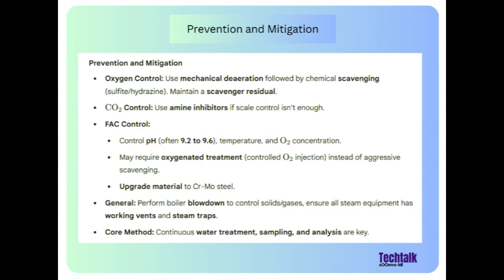Hydrazine sounds potent. It is. These chemicals react with the remaining oxygen to neutralize it. And crucially, you need to maintain a small residual amount of scavenger in the water going to the boiler. A little bit extra, just in case. Exactly. That residual is your safety net. It mops up any oxygen that might leak in later, protecting those heaters and economizers from pitting.